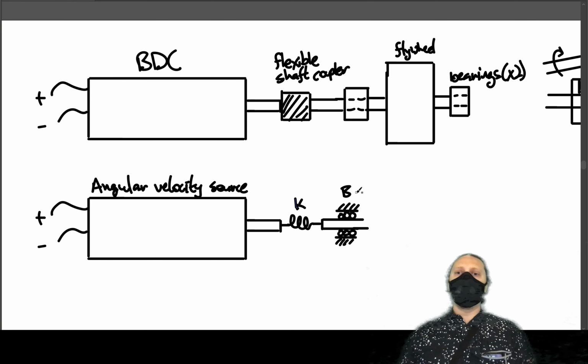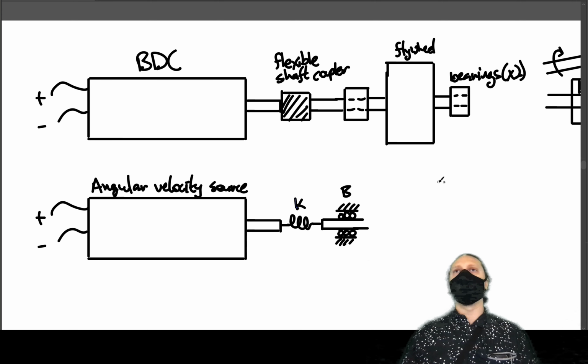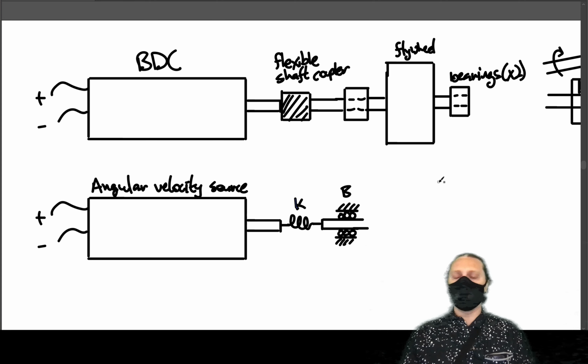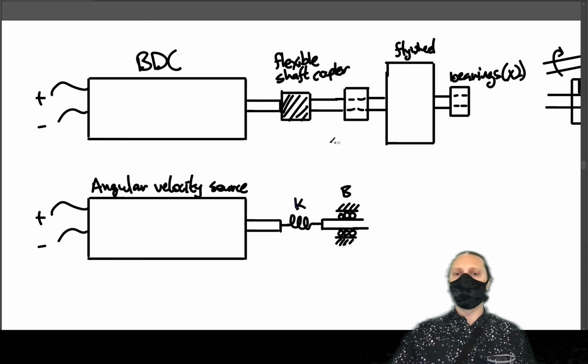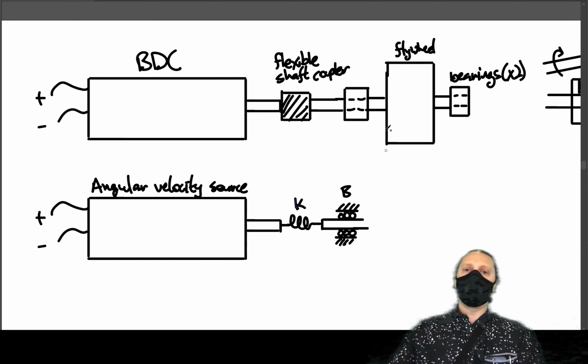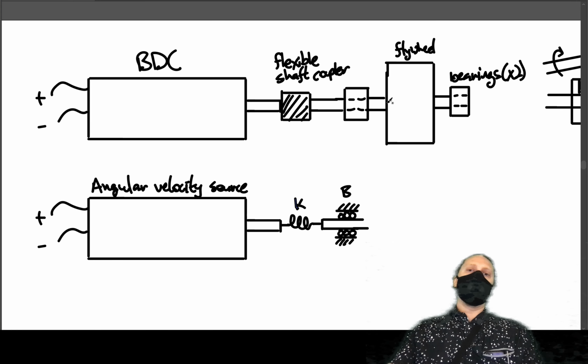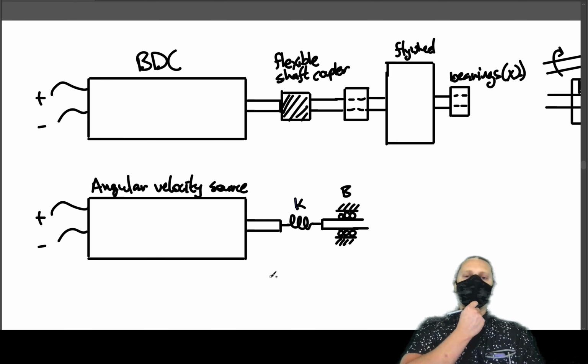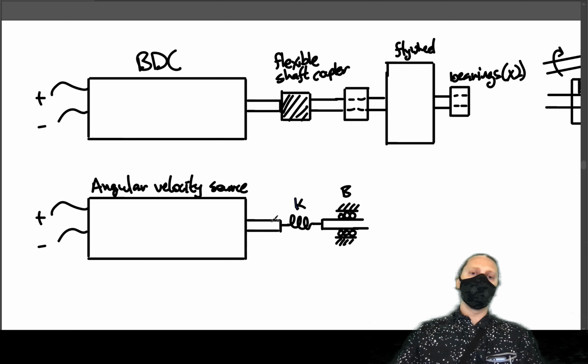If you're measuring B and you've got two bearings in there, there's no way to differentiate which bearing is applying a certain amount of force or torque versus another bearing, so you should just lump them together into a single bearing. If there was a bearing here that we were modeling and a bearing here, those would have to be different because they have this separating coupler that makes the two torques different.